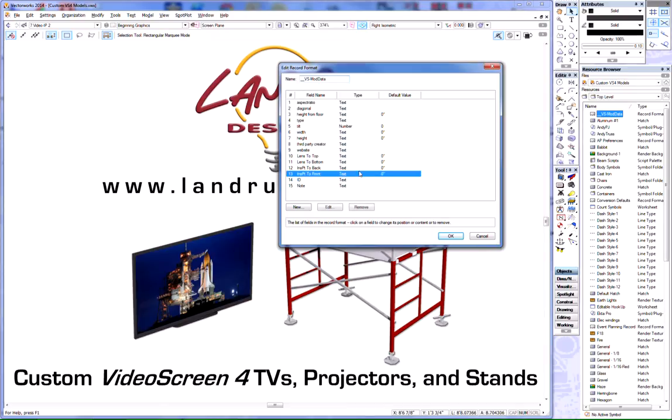First off, we've got some places here to input dimensions, but they are still simply text fields. Because they're text fields, you have to make very sure that you include your units mark. Like here I've got inches. If you don't include a units mark, you're going to end up with huge headaches. Things will not translate from user to user if they're using different units, so you could have issues there.